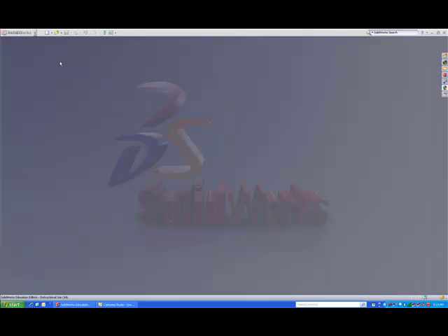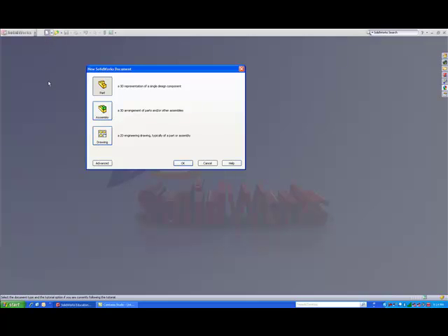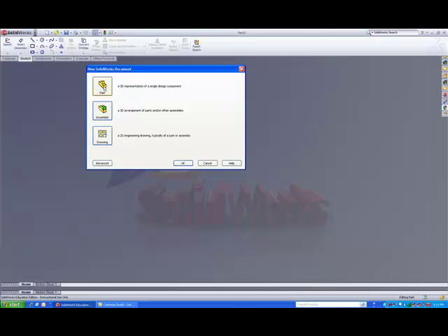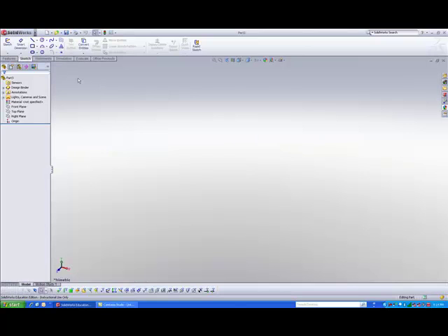In this tutorial, we will be walking through how to create a simple 3D sketch to do our weldment structure on. We need to start off by creating a part document. And if you notice on the weldments tab, the very first command listed here is a 3D sketch command. So let's take a look at how we utilize this 3D sketch command.